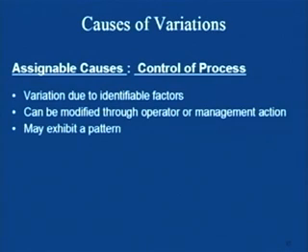Once the tool is wearing out, from one part to another part, the trend that we are getting is an increasing trend. Every next dimension we measure is higher than the previous one. Whenever we find such a pattern, we say that there is some special reason why it is happening, and we need to focus on removing such causes.